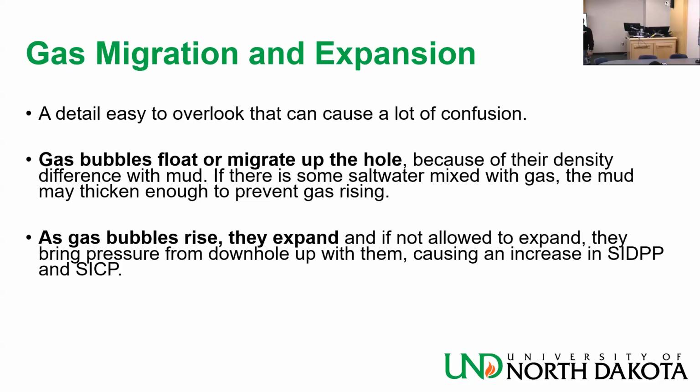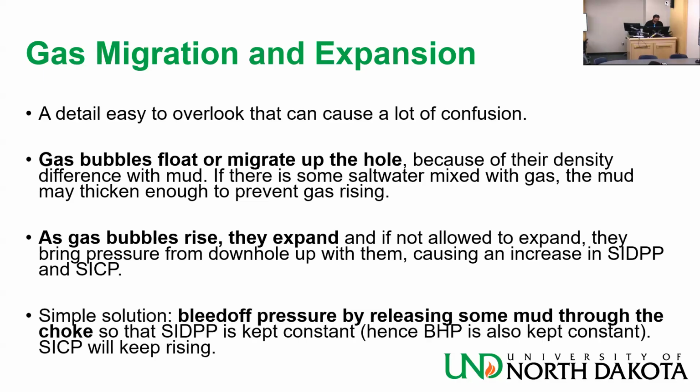Now, that example in the app back then, if you let it like this, the gas will hit the top and the pressure will be somewhere around 700 on the casing side, SICP. In that case, if the MASP is 500, you are in trouble, because by the time it becomes that, it will overcome the 500, and then you will have trouble. But if it's something like 900, then you're okay. But you need to be monitoring the pressures all the time and understand what they are trying to tell you.